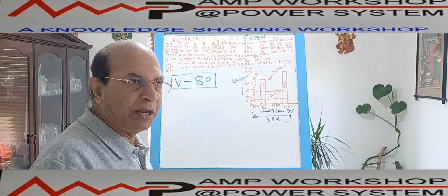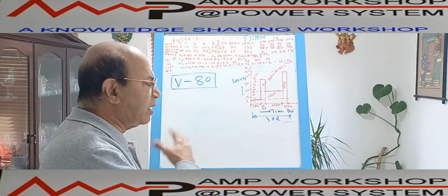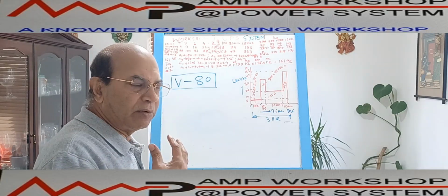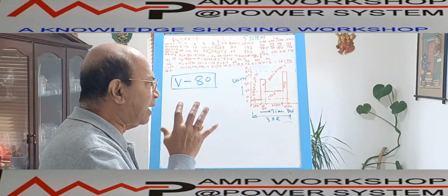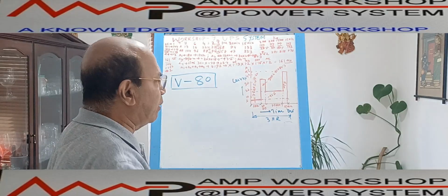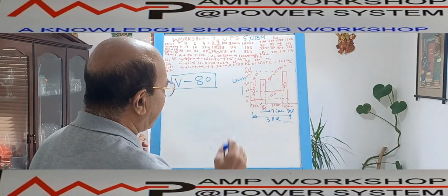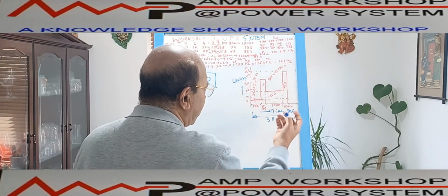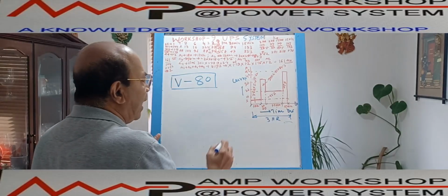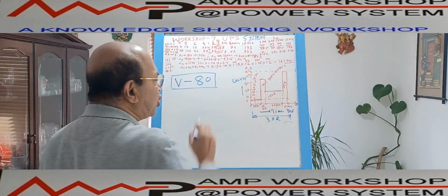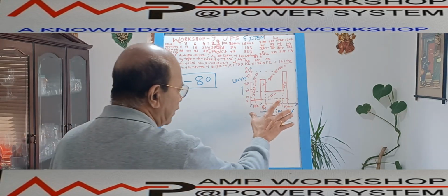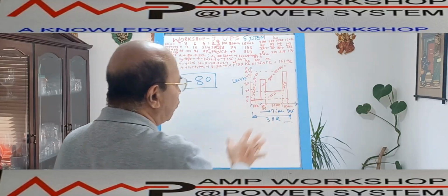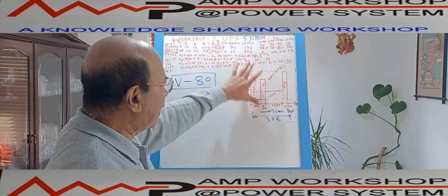As the load current varies with time, the inverter DC input current also varies, and we plot that current on a time-current characteristic. Along the x-axis we have put the discharge time, and along the y-axis we have put the discharge current. The battery needs to back up for 3 hours, and over the 3 hours we have shown how the load current varies.